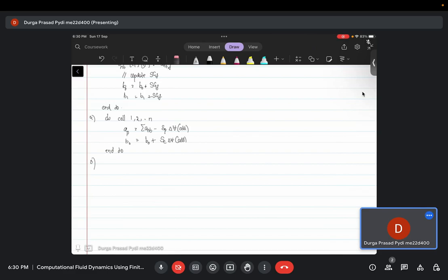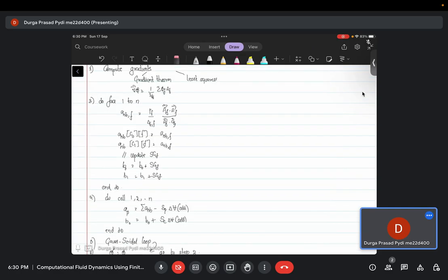So now you have all the equations, you solve them using Gauss-Seidel. Now once you are in step 5, once you solve the Gauss-Seidel, you get a value of phi, and then you will make your phi star equal to the value of phi obtained from the previous step, and then you again start from 1. And then you keep on repeating this till the value is converged.